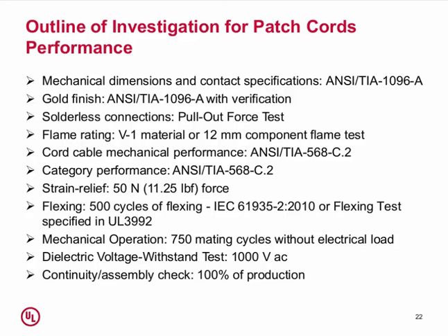The flame rating on the material, the V1 material, or a 12 millimeter component flame test. This is a requirement that's been around going back to the telephone modular jack days. The V1 material is derived from the requirements in end product standards, such as UL 6950, UL 62368.